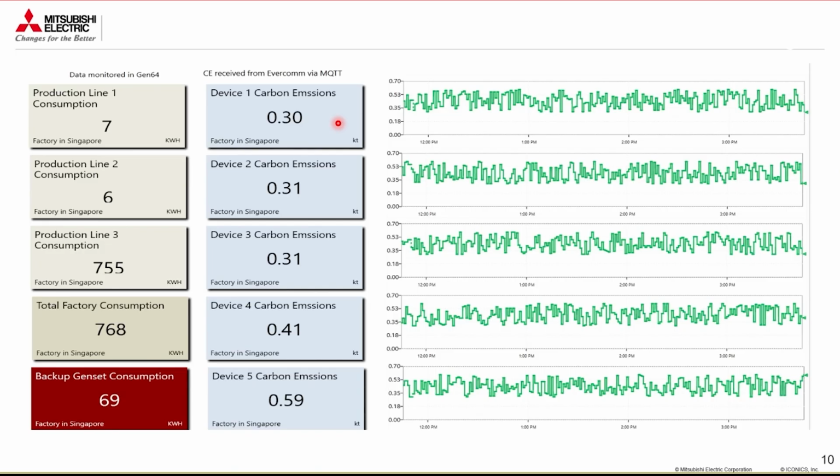Yeah, so basically we collect data from PLCs and controllers, and with MQTT broker, we publish this data to a third party, and they have their own application for doing some machine learning and analysis, and they produce some results, and we can use those results back through MQTT as well as web service back into our applications and in our control. So that's a good one.